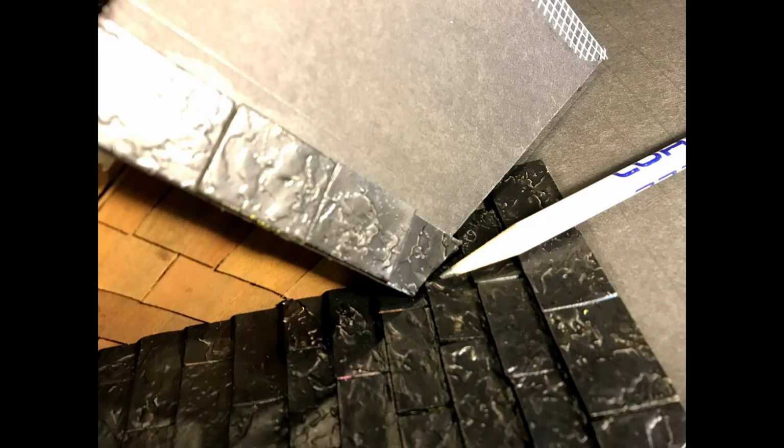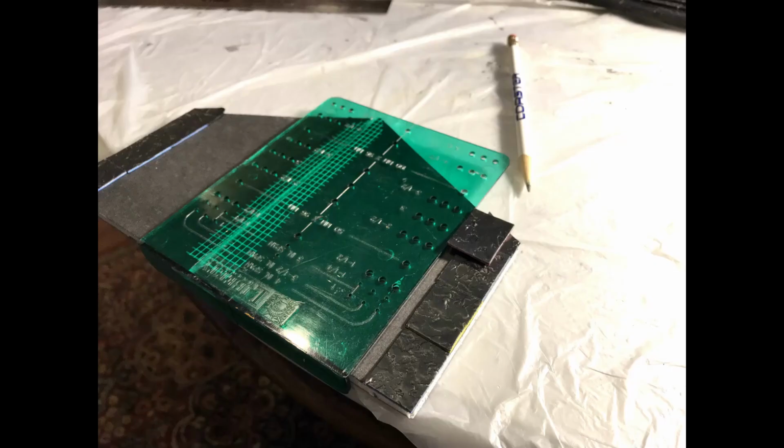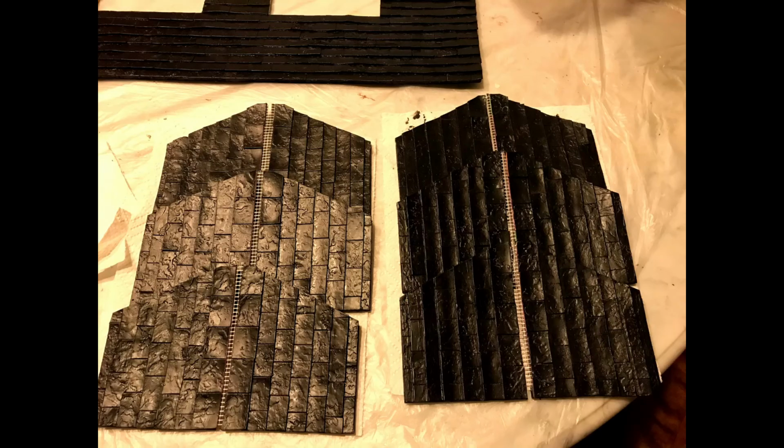With the dormer roof in place, I marked the location of the bottom edge where the shingles would align to the house shingles. I used a perpendicular fixture to mark the location of the horizontal upper guideline for the row of roof shingles. The shingles were applied in the same manner as the roof shingles. Please see this video for further details.